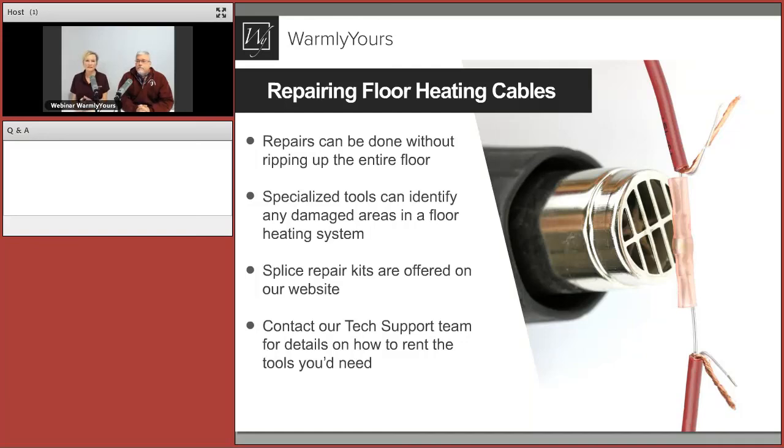So the key to not having to repair a floor, because guys, let me just share this with you. 80% of the time, the damage to a floor heating system is done during installation. Would you say that might even be higher than 80%? Yeah, what happens is people come in and they put tile down, and then the guy that comes back 2 weeks later to clean the grout lines with his sharp metal blade doesn't even know that there's heating in the floor. So he gets in there and he cleans out those grout lines and makes 24 cuts in the wire. So the key is to test when you get the product, during install, and at the end.